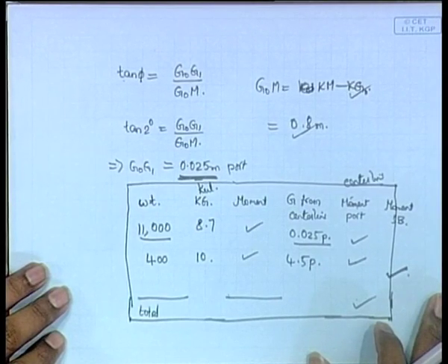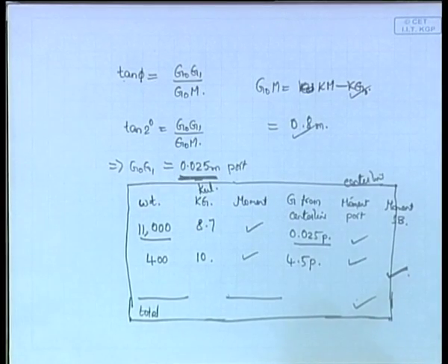Well, actually, I am calling it moment, but it's not really moment. What we are doing is finding the net KG. Moment means there is one weight here, one weight here, one weight here. Because of this, what will be the net centroid of this whole weight? So this product is what I am calling a moment. That's all. It's not a moment as a vector, you are thinking of it. That's not what we are doing here.